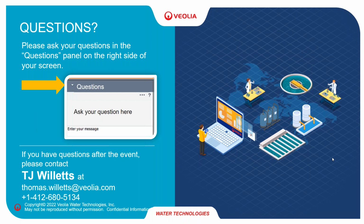As you get to the other units, up to the RVF, you have a blower that has some maintenance requirements depending on the application. It could be as long as every 3 to 5 years to as frequent as every year, changing the blower and sending it out for rebuild. My rule of thumb is that with a PCF unit, somebody takes a reading a couple times a week and watches it to make sure it's functioning properly. With the RVF unit, you typically have somebody taking readings multiple times a day. Everything's collected on the screen so you can monitor all the data, but somebody definitely needs to review it and make sure it's functioning properly.